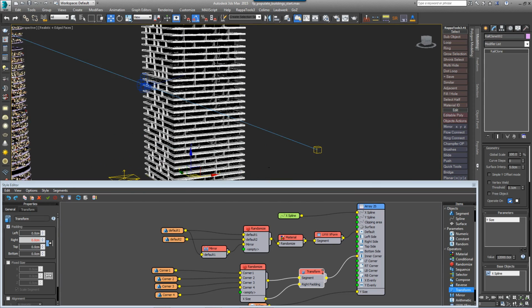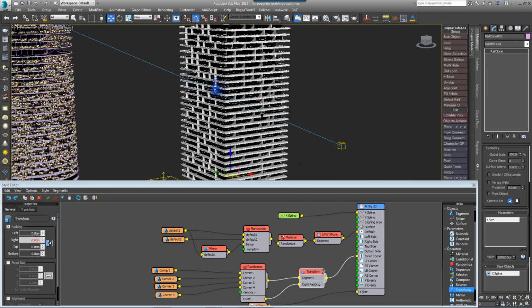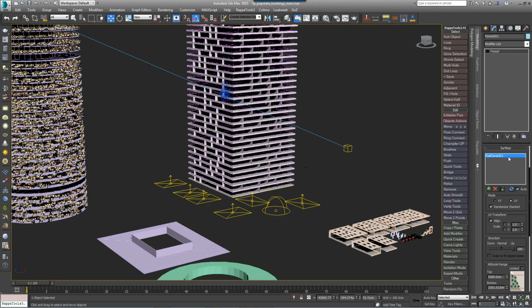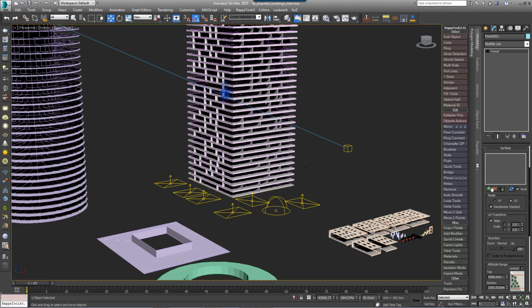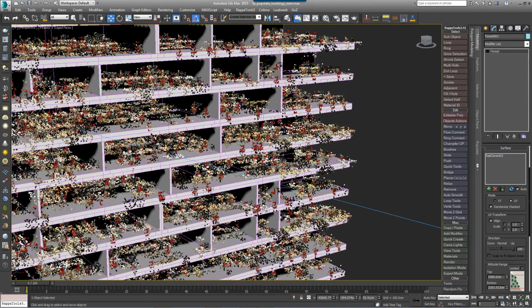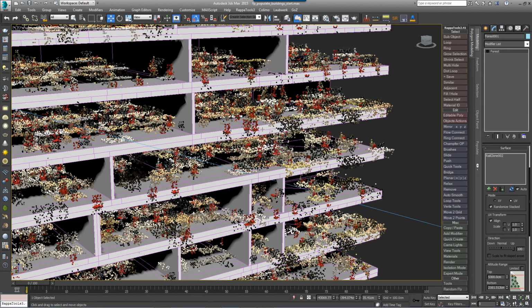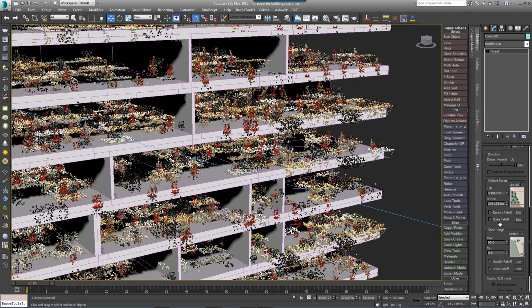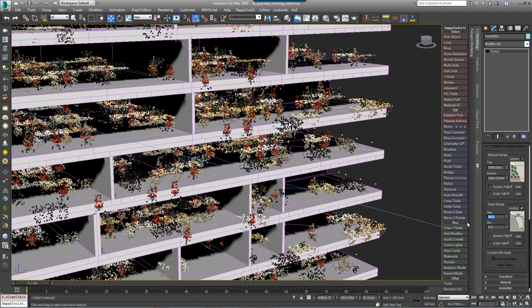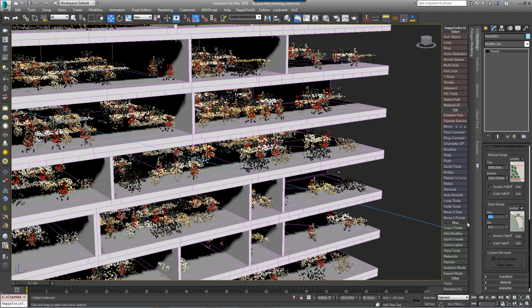And this completes the building interior. We can now apply the forest object to it. So select the desk's forest pack object that we created earlier and open the surface rollout. Delete the existing surface and add the new RailClone object instead. You'll notice that the objects are being scattered on the ceilings and the walls. To prevent this, we need to limit the scatter to only those polygons which are facing upwards. You can do this using the limit to slope controls in the surface rollout. Turn on slope range limited and enter a maximum value of 5.